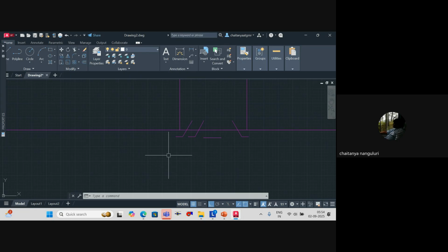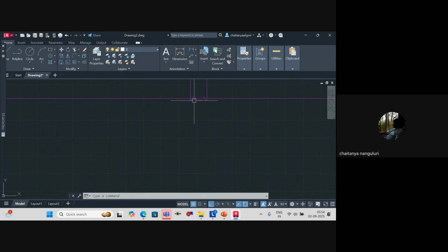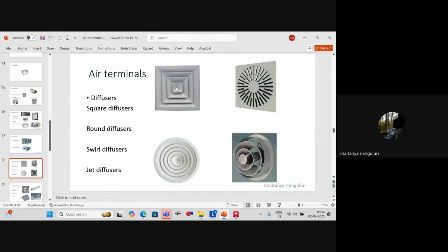if you have used it, people under it will always have headaches, because cold air will be hitting them. Whereas when you use a diffuser, the whole air is diffused to the ceiling and then comes down. Because of that, there is no concentration of air hitting anyone's head. Understood? So we go for this kind of diffuser, either square or round, depending on the aesthetics.